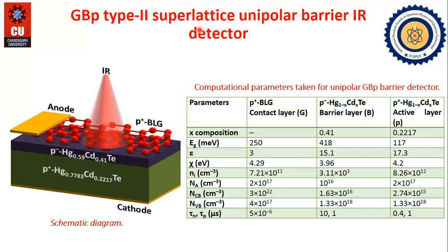Among the various materials, graphene mercury telluride heterostructures are found to be a favorable type 2 superlattice choice due to their tunable band gap and self-passivated surface, and can be used to develop IR barrier detectors where interface defects and lattice mismatch can be avoided. Among these several graphene and semiconductor heterostructures, the graphene mercury heterostructure is chosen to demonstrate superior optoelectronic capability in the IR spectral region.